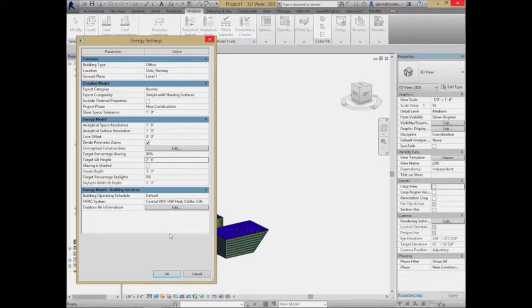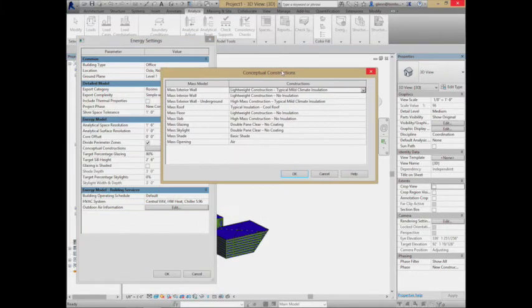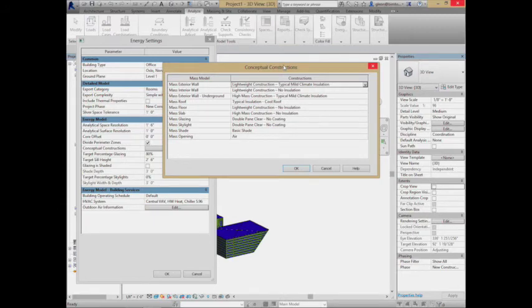Now, as we're letting it run there, for the different surfaces, there are some assumptions built in, in terms of what the exterior wall and the interior wall construction is. Like, this is a mass exterior wall that's typical for a mild climate. Oslo probably doesn't qualify there, so this will probably be a fairly leaky building in that the R values, the resistance values in the walls, probably aren't as high as they should be, but the analysis will tell us that.